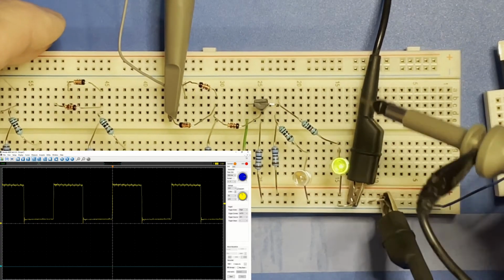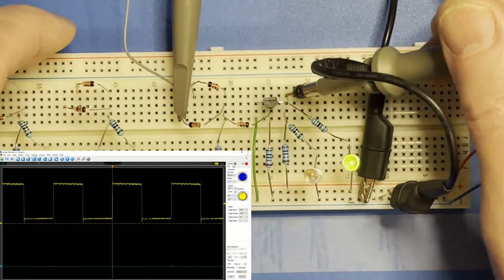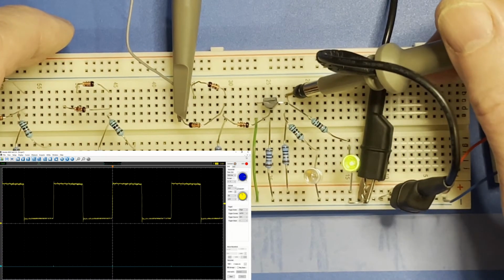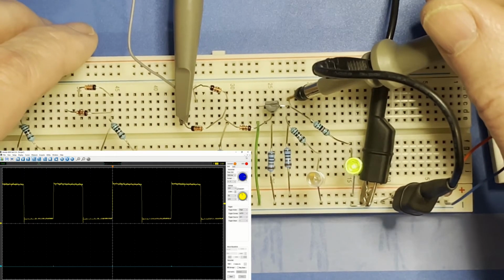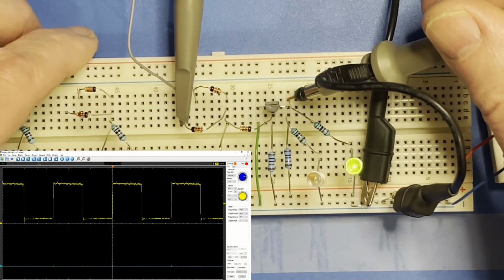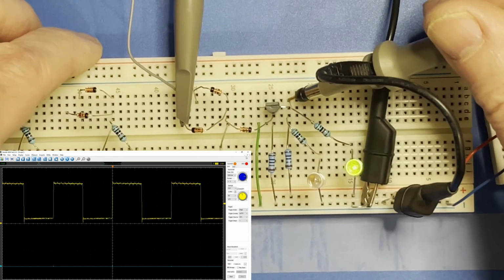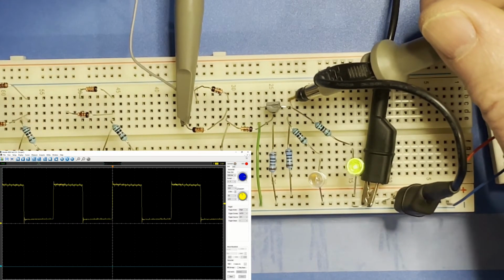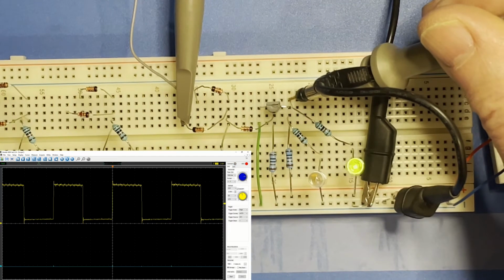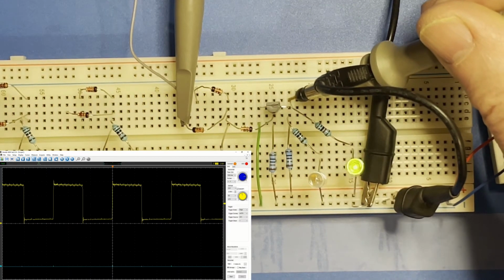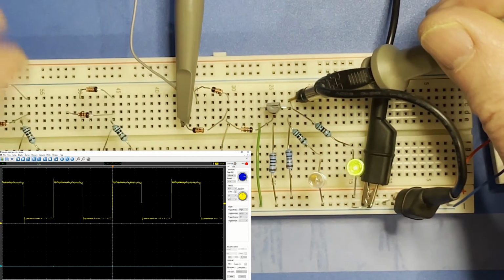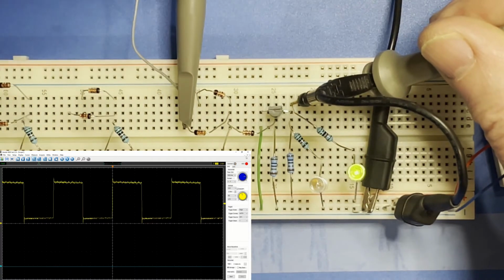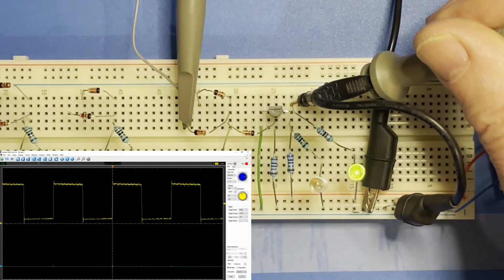Go to the collector and it's grounded. That transistor is saturated all the time because it's being driven hard enough that it never has time to unsaturate. The charge carriers in the silicon never have a chance to dissipate when the base voltage reduces slightly, and it doesn't turn off. So as a practical gate, it doesn't work at anything but very low frequencies.